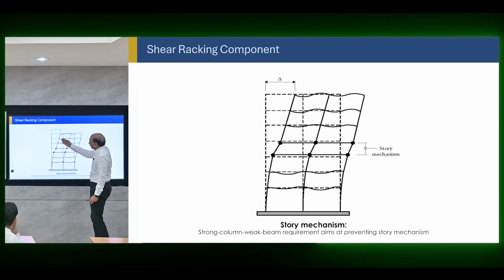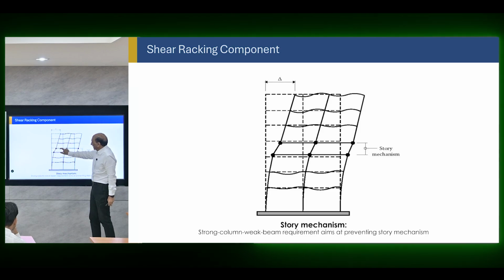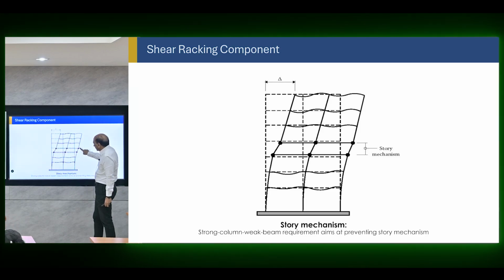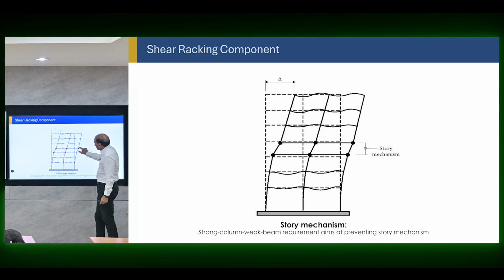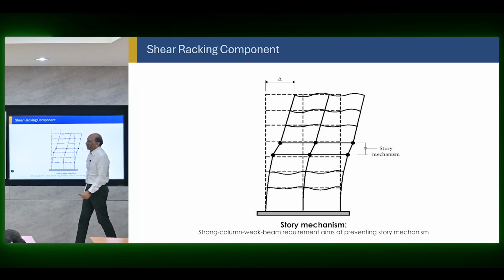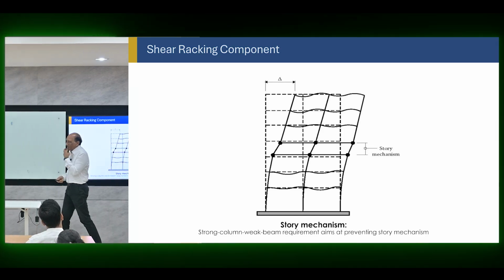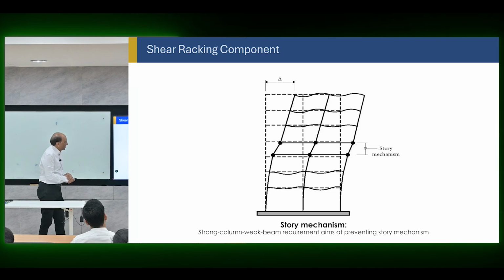We have a frame that goes like this one. Each story has a kind of a mechanism. So each story has what we call a drift as a shear. So there's a net shear effect of the story, which is one story moving this way, another story moving this way, and then displacement divided by height will be the one, and that's the total displacement. We already talked about these two factors. This is a frame behavior that we typically see.